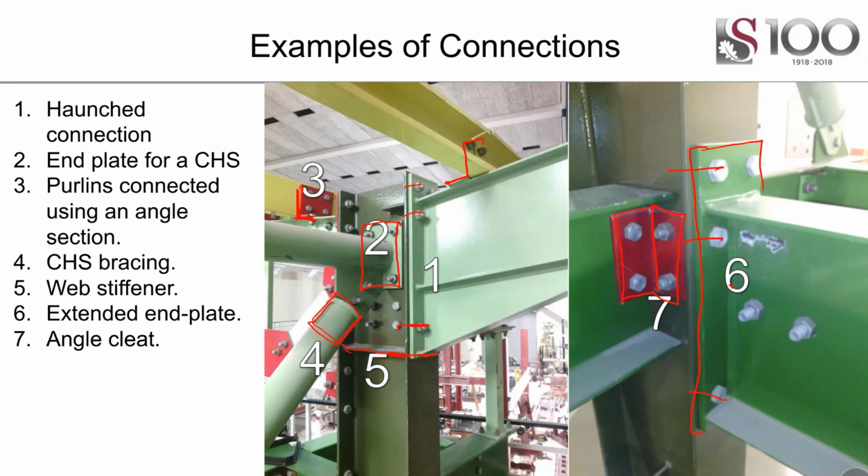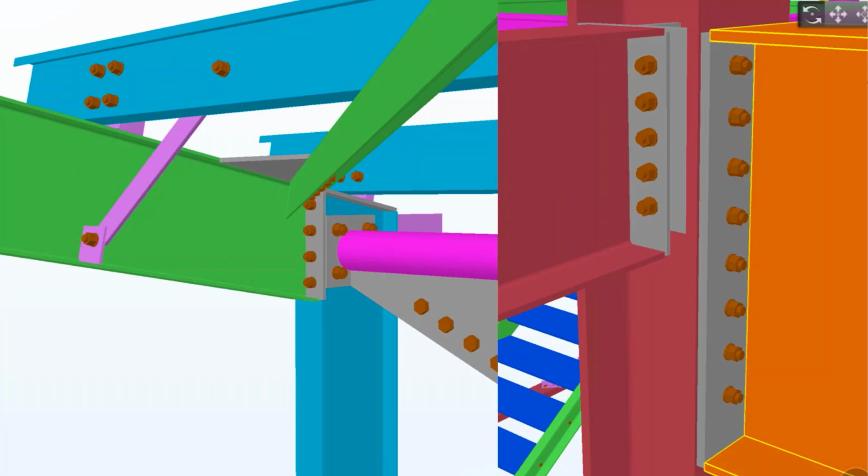And you can envisage a steel structure as a giant Meccano set, and you need to decide how you are going to connect this thing together in an efficient way, because at the end of the day, connections can account for a lot of money. The cost of the workshop and the welding and the different details and bolts, etc., can add up a lot. And good connection details, simple connection details, can bring down the cost of a steel structure a lot and make it a lot more efficient. And also, using standardized connections, you can result in fewer mistakes and fewer problems, and generally a more reliable structure. So consider connections very carefully.